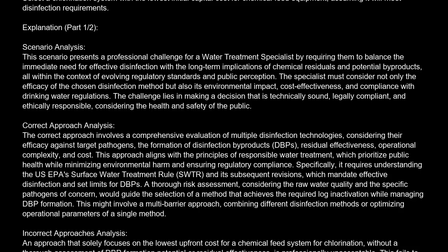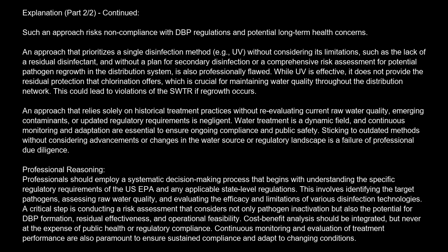Incorrect approach analysis: an approach that solely focuses on the lowest upfront cost for a chemical feed system for chlorination, without a thorough assessment of DBP formation potential or residual effectiveness, is professionally unacceptable. This fails to meet the comprehensive requirements of drinking water regulations, which extend beyond just initial treatment to include the quality of the finished water delivered to consumers. Such an approach risks noncompliance with DBP regulations and potential long-term health concerns.